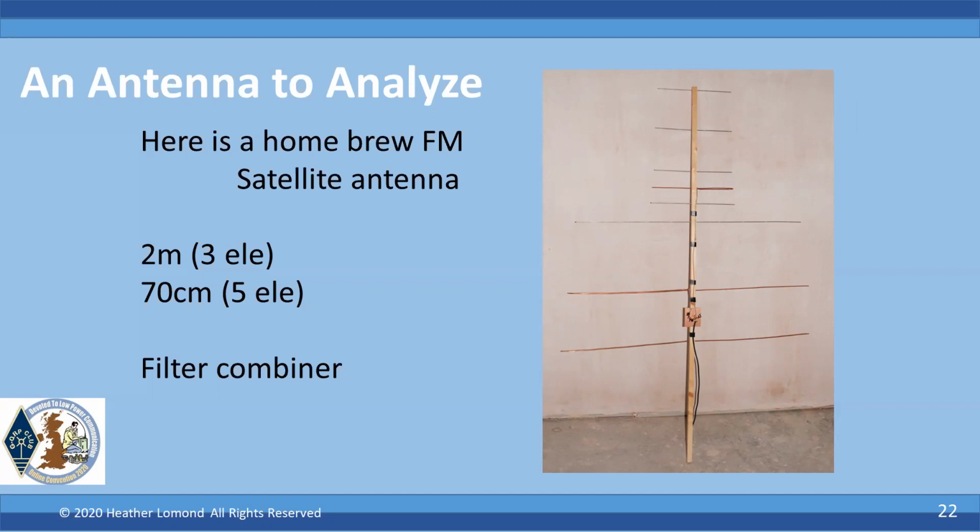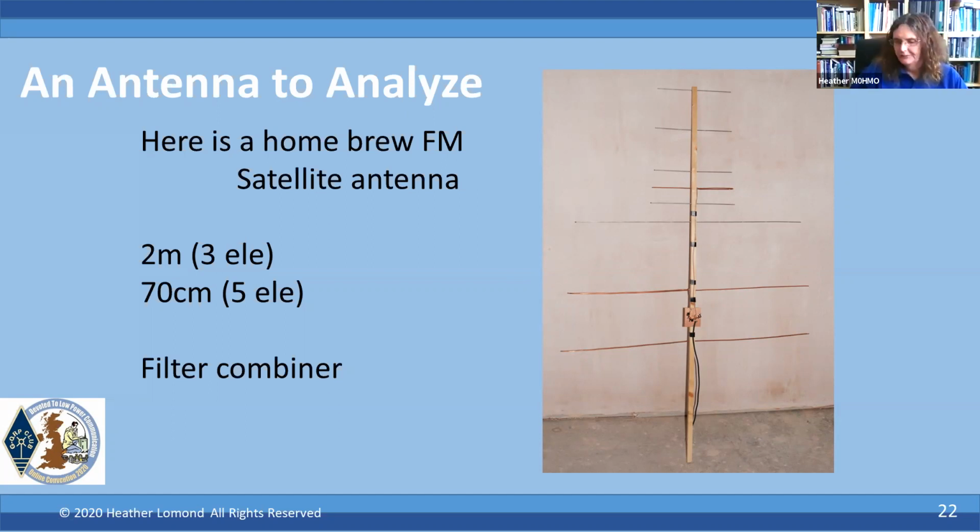Okay, there's a question here about measuring active devices, such as a transmitter without attenuation. I think I know the answer to that, but I'll let you. You have to be very careful, but yes, you can. I don't know what the spec capability of the input port to the NanoVNA is, but yes, be very, very careful. I would put attenuators in, but yes, you can measure to some extent by doing that kind of thing, but not, as we've said, in SWR. You have to measure the S21 parameters.